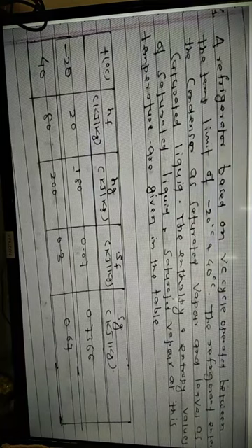So this temperature limit is -20 degrees centigrade and 40 degrees centigrade. That means this TL, the lower temperature, is -20 degrees centigrade. At this lower temperature the evaporator runs, and the condenser runs at 40 degrees centigrade. That means TH is 40 degrees centigrade, right?